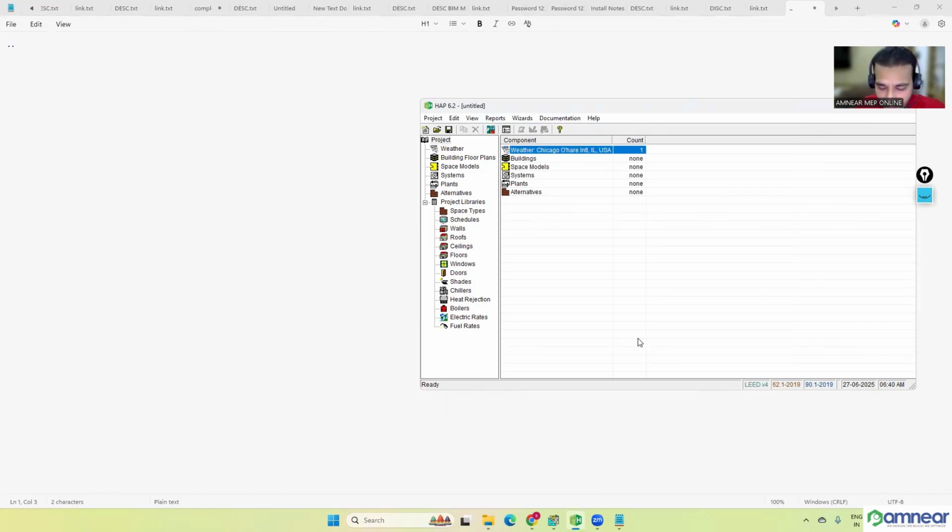Okay. Now, before that, how can we upload the gbXML? In the BIM session or the Revit session we have already explained, we create the architecture spaces, and after that when we do the mechanical, we create the HVAC spaces and so on. After that, we export that into the gbXML, an XML file. That file we can take here.